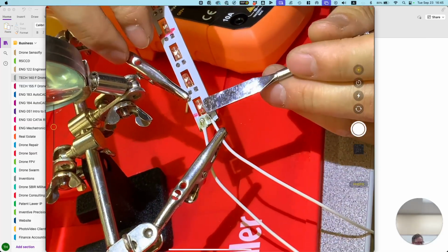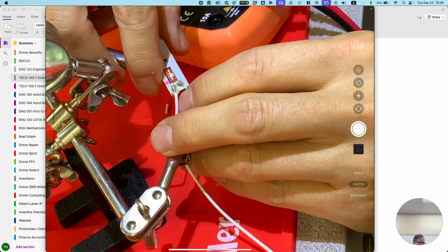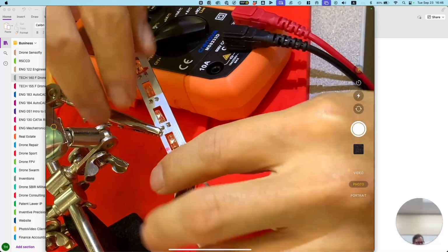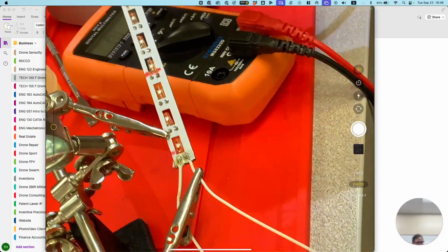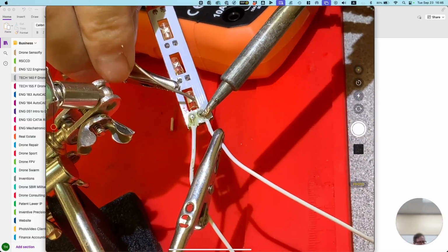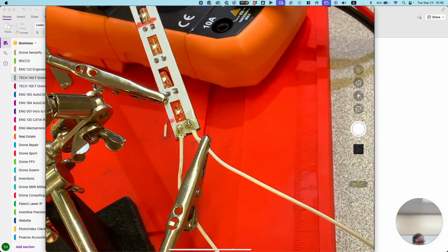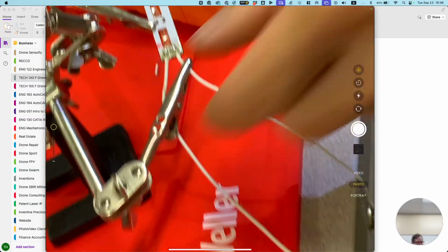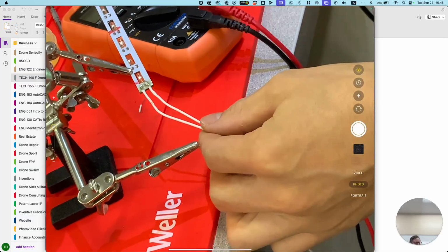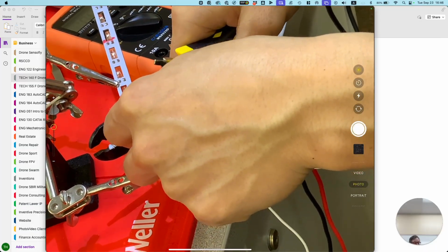Okay. Put some more flux on there. It doesn't move at all? It's pretty solid. It doesn't move around. I want to make sure it's not hovering, but it's actually sitting. There it goes. There you go. Solder. Okay, cool. Once again, I'm gonna solder the joint. Done. All right. Now I'm just gonna clip these ends right here. We don't need it very long because this is literally supposed to be one after another.